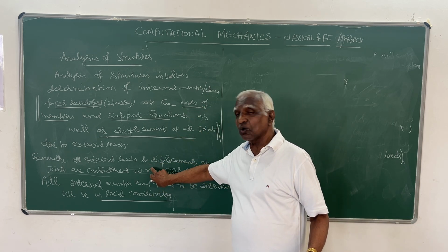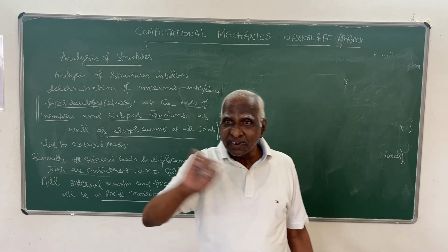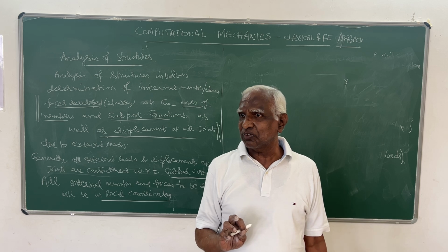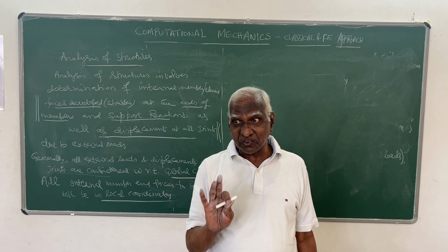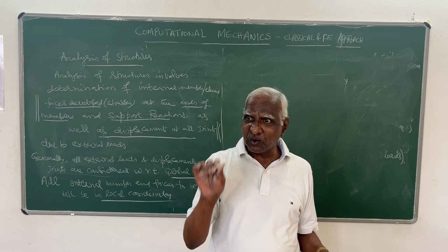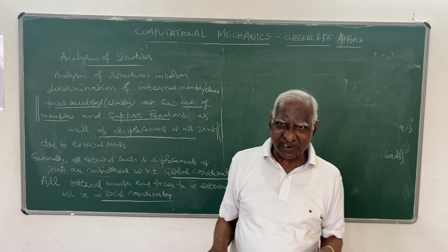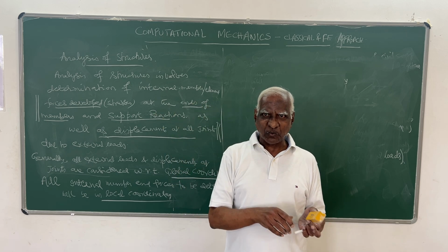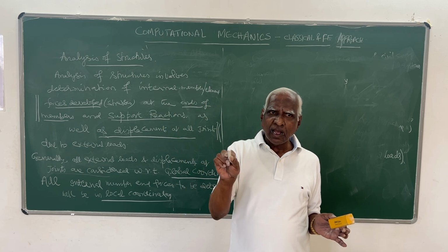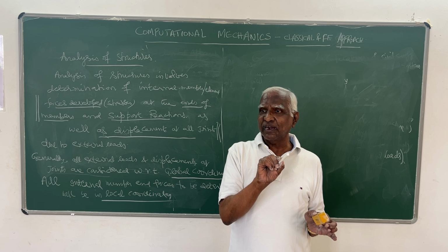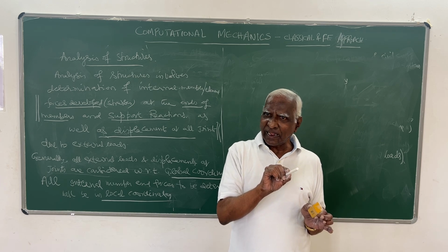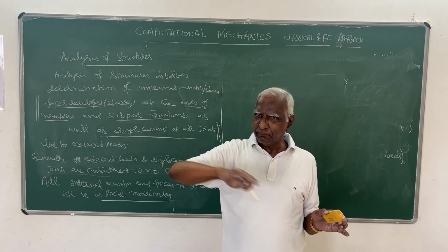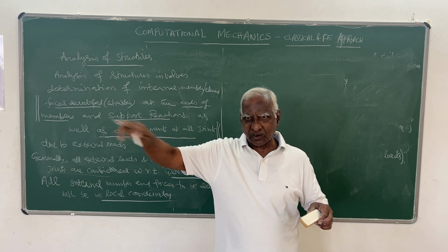Then the internal forces. We have to identify the internal member force or element information. We have to formulate. Carefully you observe. Whatever I am talking about, it has sense now. The essence of analysis: the internal forces are always with respect to element coordinate. Element coordinate means always first in the element we have to identify the origin. Then one axis. One axis has to be linear direction, along the central axis.